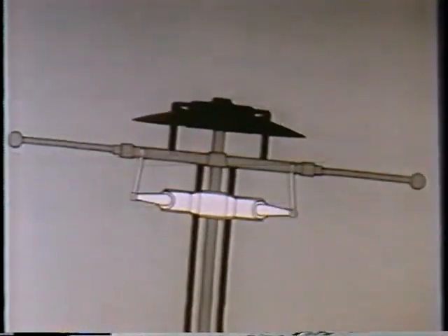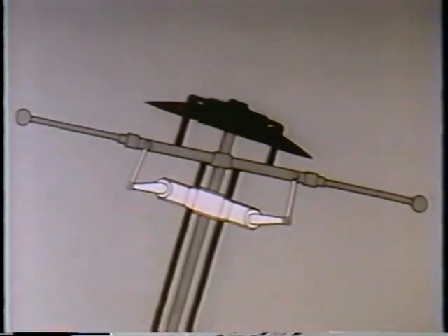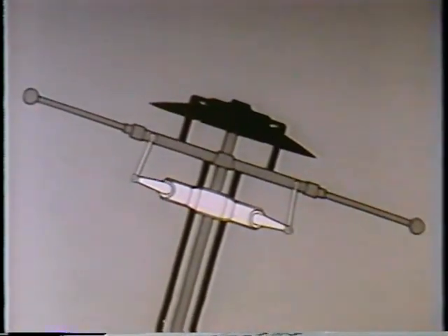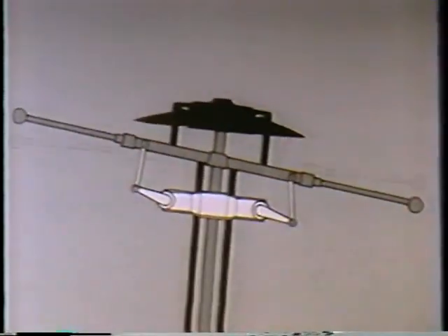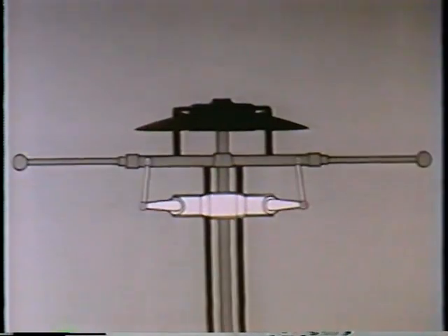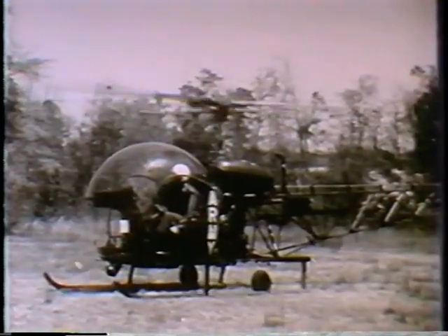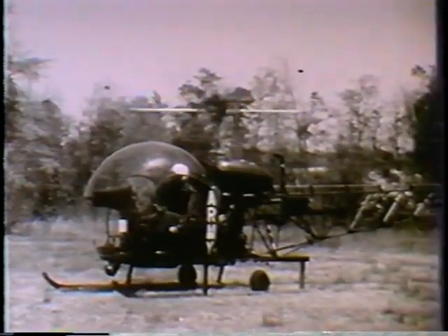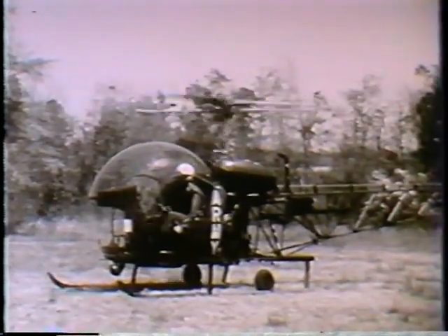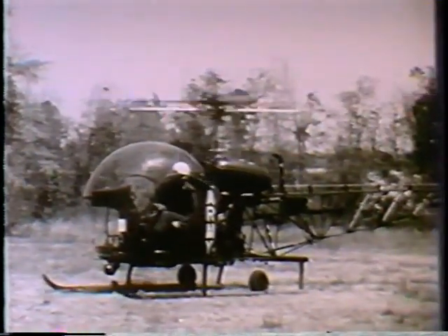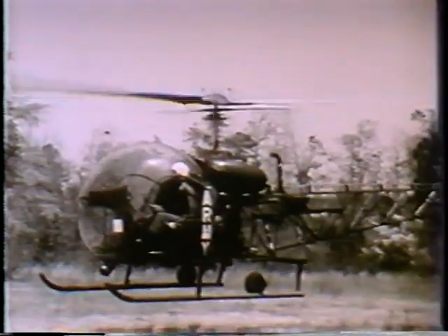Since any disturbance affecting the rotor or fuselage would rarely last more than a few seconds, we suffer no effective loss of stability, and the dampers give the pilot greatly increased control. The stabilizer bar, then, because of its gyroscopic property of rigidity in space, is able to modulate sudden changes in attitude of either the rotor or fuselage.